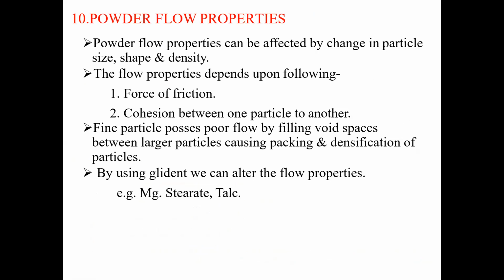Next, other flow properties: fineness of powders. The powder flow properties can be affected by changes in particle size, shape, and density. The flow properties will depend on the following: one is the force of friction, and another is the cohesion between one particle and another. Fine particles possess poor flow by filling void spaces between larger particles, causing packing and densification of the particles. So by using a glidant, we can alter the flow properties.